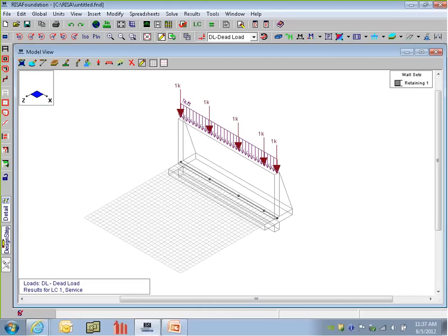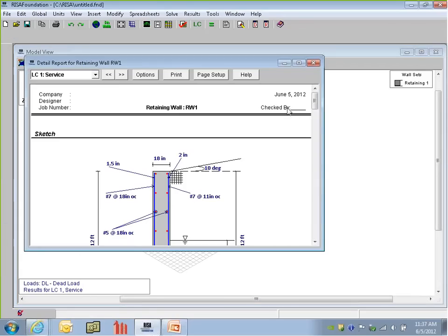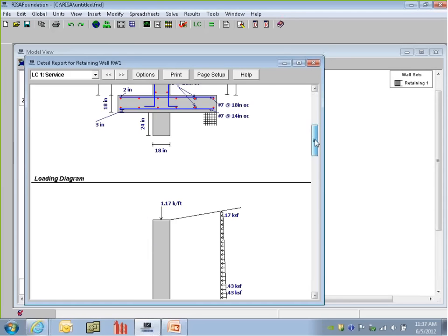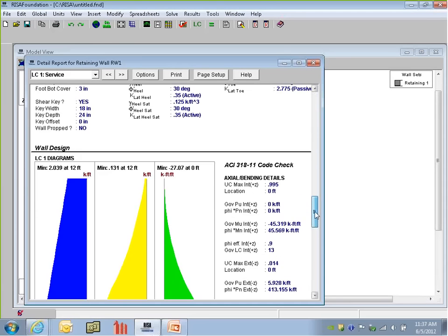Maybe we had a 50 kip load, something really high coming in, and we really wanted to focus on that design, carrying that well in that one area and not spreading it out. What you might do is just draw segments of walls, pieces that break it up a little bit so you can really get those stress risers inside of the wall. Otherwise, we're just going to be taking that whole wall on an average, which is typical for concrete, but if you are looking for it to spike, you might need to break up your wall.